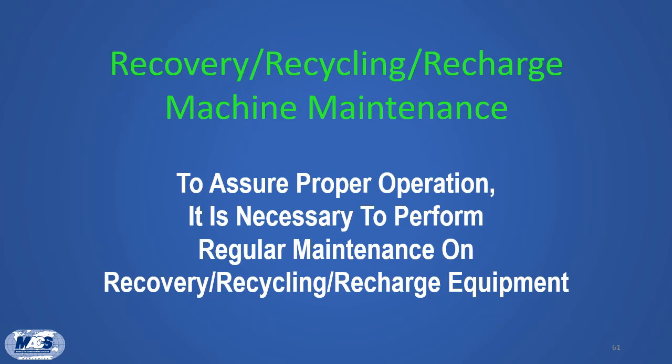Your shop tools and equipment require maintenance if you want them to operate properly. Let's look at a few specifics. Recovery, recycling, and recharge equipment should be checked frequently to ensure that no leaks exist within the internal refrigerant flow circuits, as well as the external hoses and seals. Regular maintenance of your recovery, recycling, recharge machines should help to ensure that SAE standards for purity for recycled refrigerant are met.